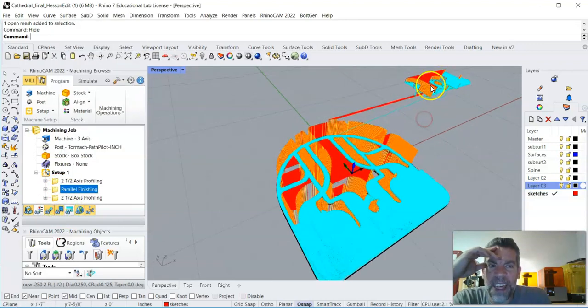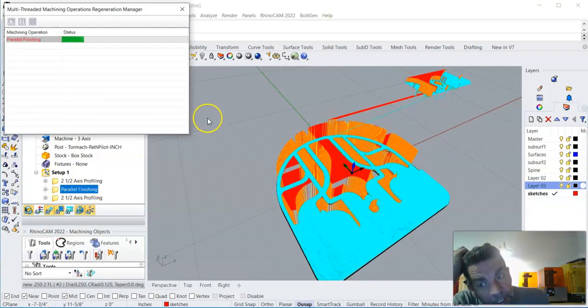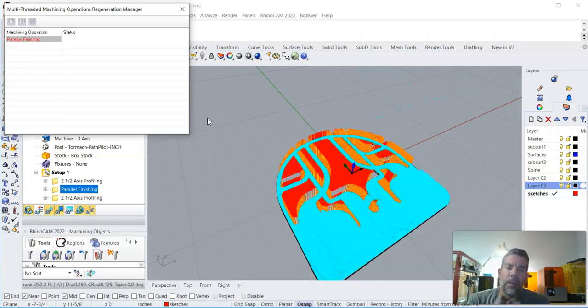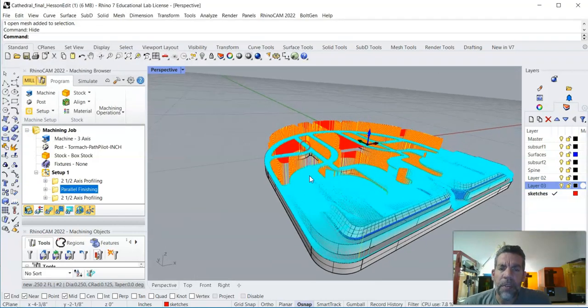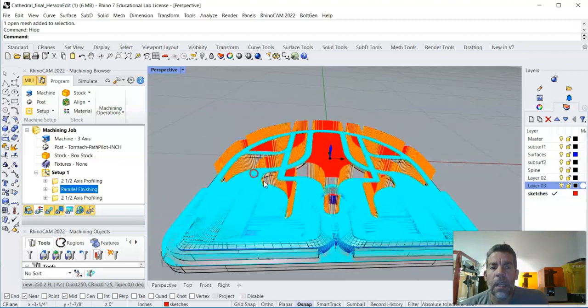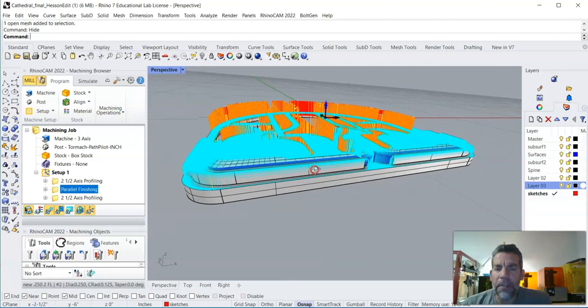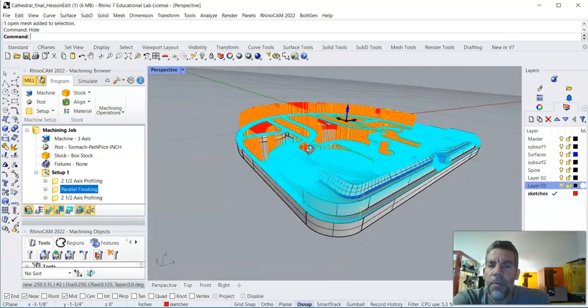I think that's why you were getting that. Actually, I turned that on so it generated a path there, so let's regenerate that now that that's hidden. I think that's why you're getting that artifacting, because there are still some things that aren't quite unioned, or aren't setting on top, or are overlapping. So you can see now there's a couple things we can change. If you're okay with the way this looks, I'd say just run it the way it is. If you want to go back and fix those things, then you'll probably have to remodel. But I do want to show a few other things.